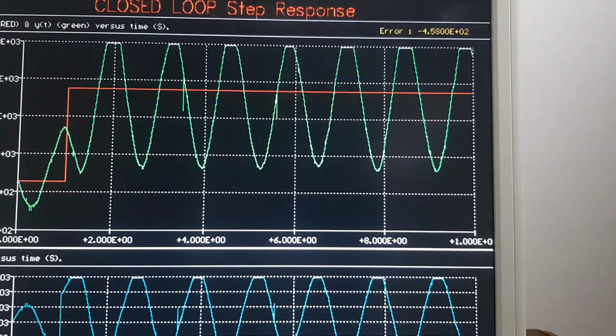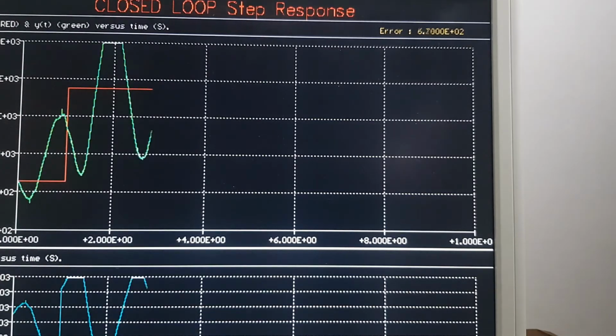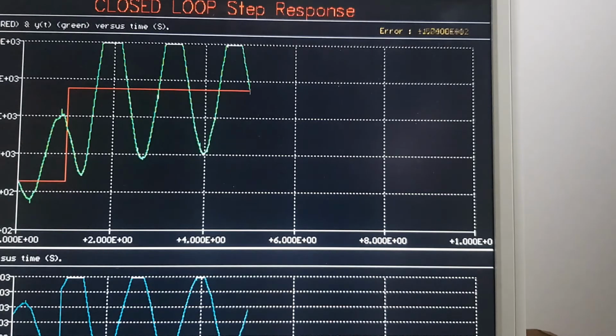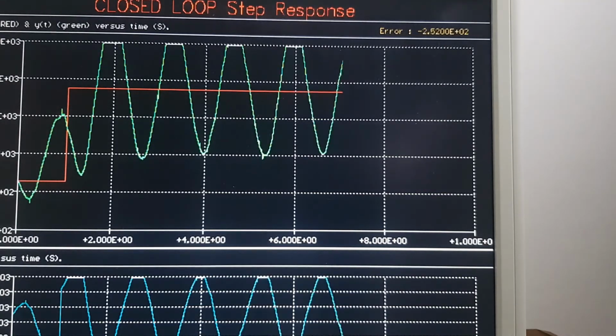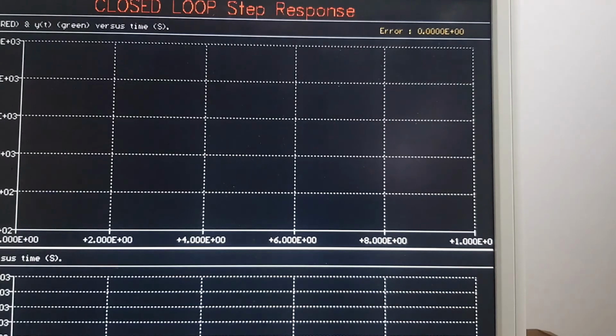So this is a marginally stable response, and in this particular case we can also call it a limit cycle. And this is where the control system is not very good at all. So if we overcook the gain, that's at 2, then we're going to get this type of not very good response occurring. The actual system we've got here can't go unstable because of a limit on the heater values.